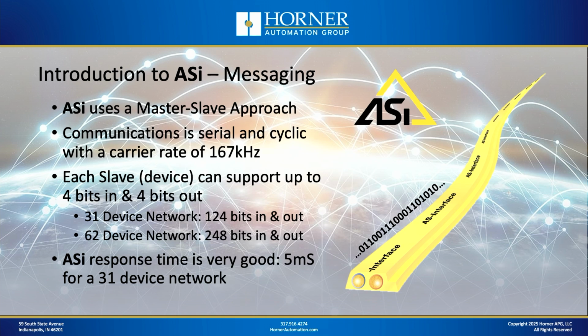Now, as I mentioned before, you can have up to 62 devices on the network. And if you do, in that case, you're going to have 248 bits in and out. But a basic ASi network would be 31 devices with half that amount.